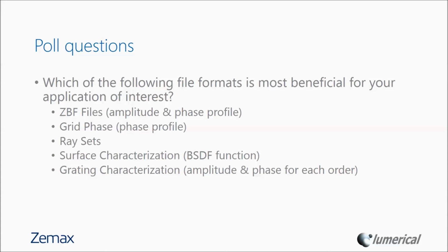Moving down the list, the fourth bullet point here: Lumerical can also generate BSDF files for use in OpticStudio, and these are for simulating scattering profiles. So Lumerical software can simulate the micro and nanoscopic interactions of light with a rough surface, and then that is used to generate a BSDF file, which OpticStudio then uses for the macroscopic ray tracing through the rest of the system.